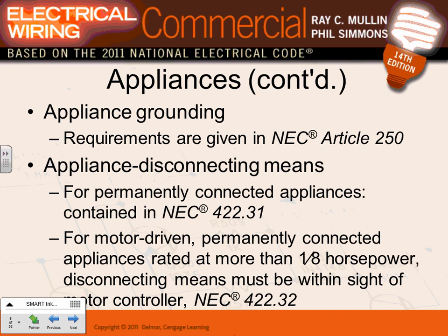The other one, appliance grounding. All appliances must be grounded, period. So you have to pull an equipment grounding conductor based on what? Jeff, based on the overcurrent protection device. No rocket science. Appliance disconnect: you have to provide a disconnect for all the appliances that you have.